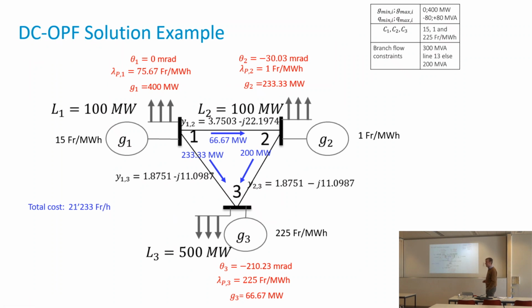I solved it. Now it's very simple, because it's a linear convex problem. Here I assume linear cost because the cost is simply fixed at every generator. Here is the solution I find. We find branch power flows that are now pure active power. We see that they are not very different from the values we had obtained with the full ACOPF. Fortunately, because this is how European markets work for deciding the optimal values of generation. Of course, we have ignored the losses.